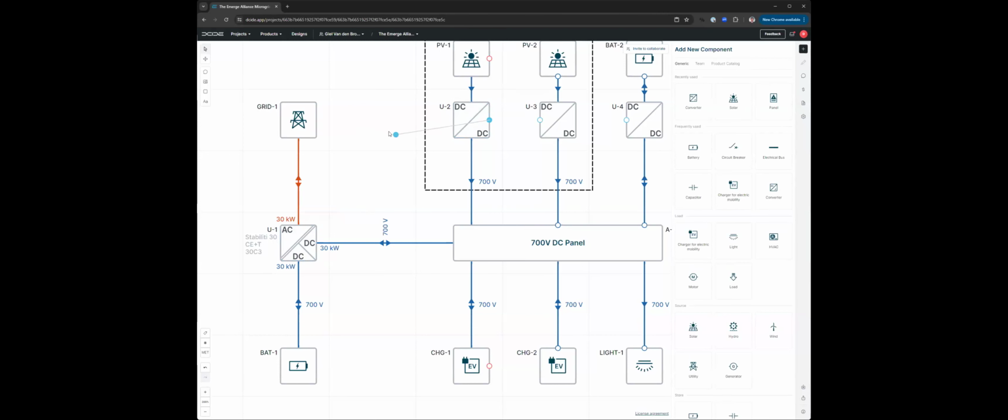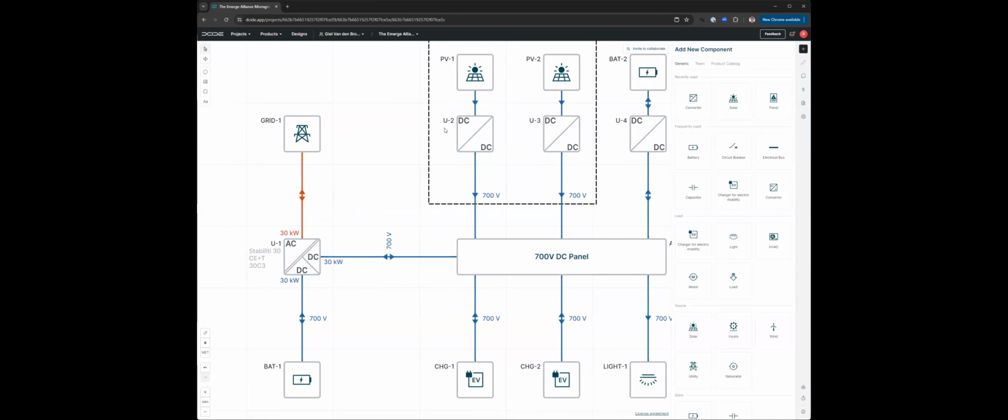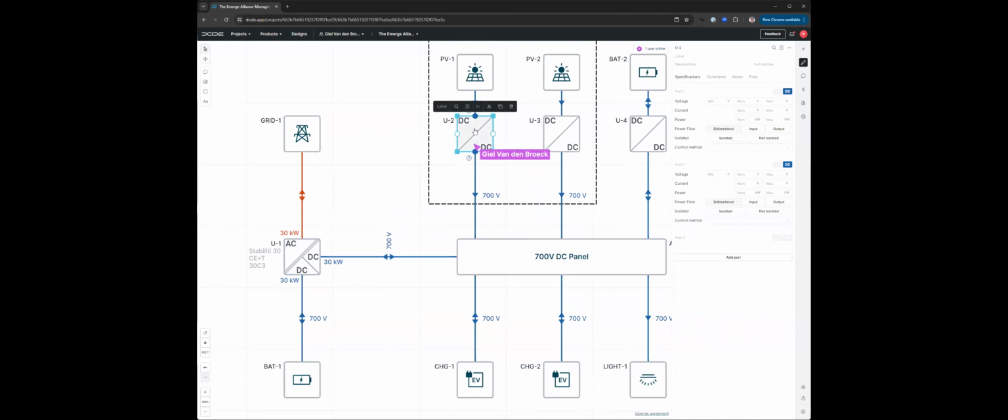And I would say isolation is important, just as a side comment. If you're doing a retrofit design with solar, an isolated converter is most definitely one of the safest ways to go, because it isolates the different grounding on the solar side and on your planned DC side.